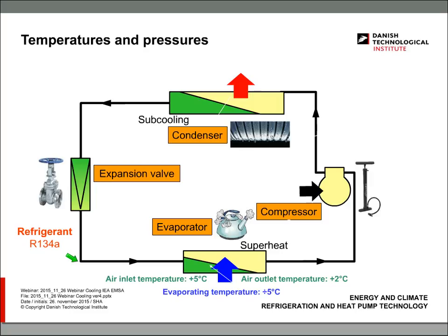then we can see on this side that by operating the compressor, it will produce a suction pressure in here. The suction pressure is also inside the evaporator, which gets the refrigerant inside the evaporator to evaporate. And instead of water, which as we know evaporates at 100 degrees, the refrigerant evaporates or boils at perhaps -5, as in this example.